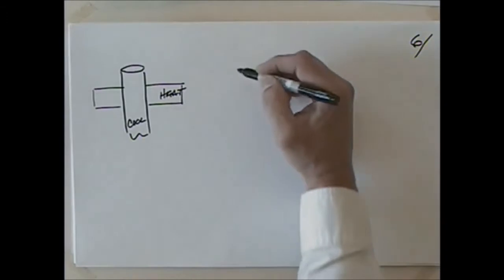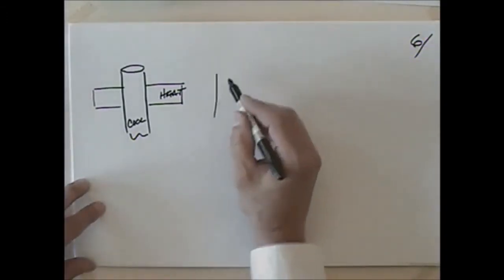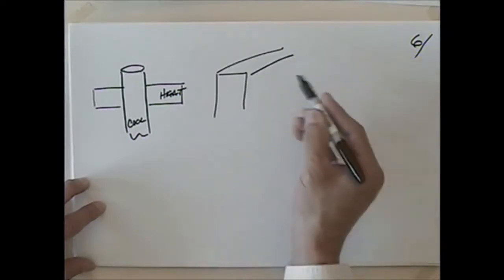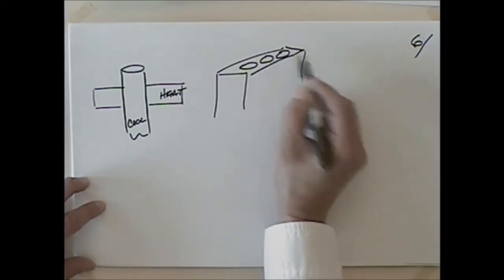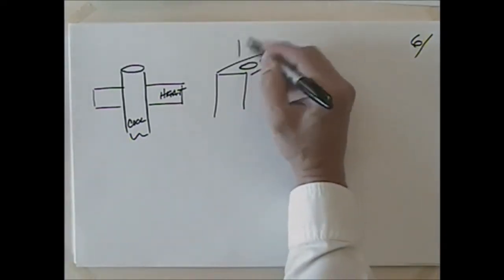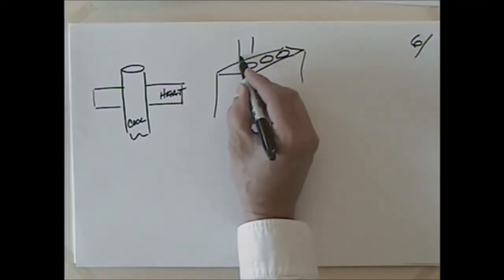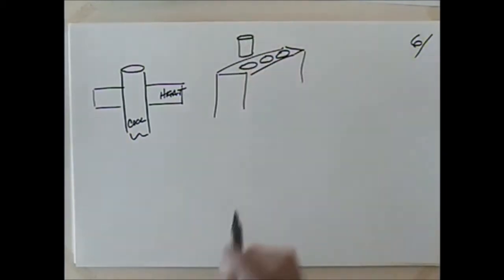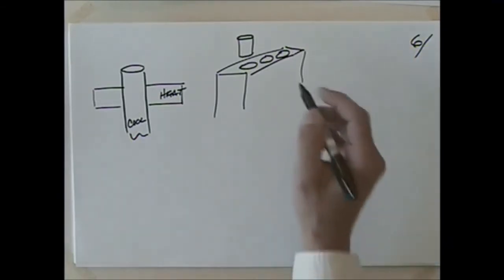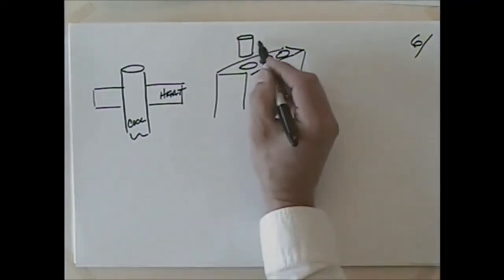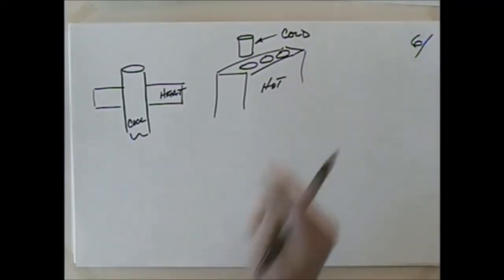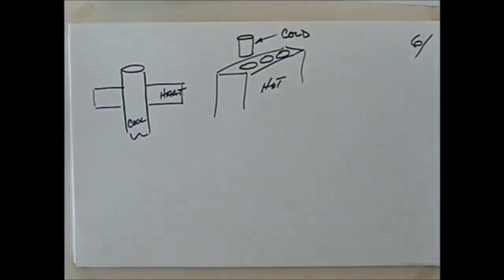They also do this in the reverse. If you look at an engine block, a lot of industrial engine blocks will use sleeves, and there'll be a wet sleeve or a dry sleeve. I guess that's a 3-cylinder there. And they'll have these sleeves that, particularly if they're a dry sleeve, are going to slide in. Okay, and it's going to be an interference fit. Really, the only thing that holds it in there is the interference. So what do we do? We roll the block outside on a nice, warm, sunny day and get this thing hot. Okay, and what do we do with the sleeves? Yeah, put them in the freezer, get them cold. Okay, and then don't waste any time getting them in there.